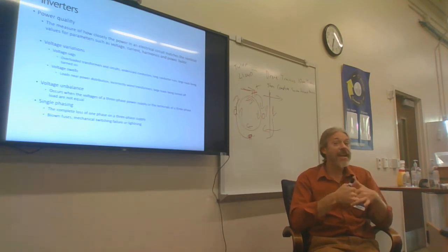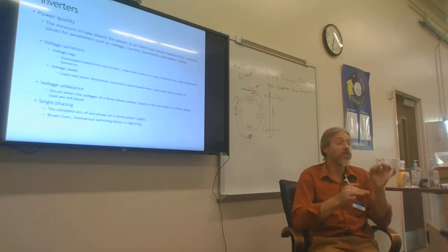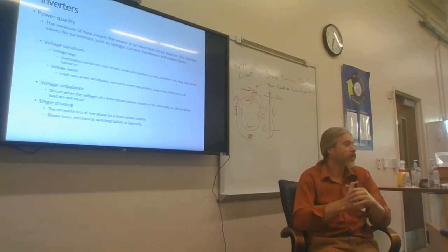The amperage to operate that refrigerator is going to have to go up by about 30% because the voltage went down by about 30%. Is that 14 gauge wire capable of handling 30% more amperage? It might not be. That's where long conductor runs or small conductors are troubled during voltage sags.